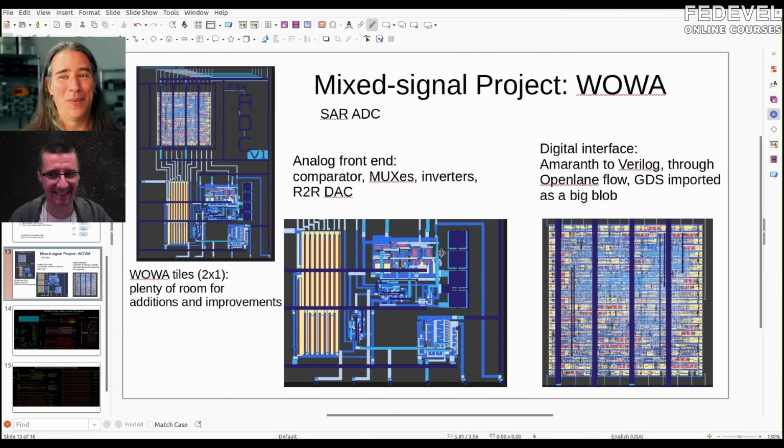So, okay, capacitors, they're very small. When ngSpice doesn't converge, when it has trouble, I would just let R shunt. You just add this option where you say shunt everything, using 10 mega ohm or something, and then it converges. Cool. Well, my system started misbehaving, and it's because the capacitors were so small that 10 meg was way too small a resistor. It was draining through it.